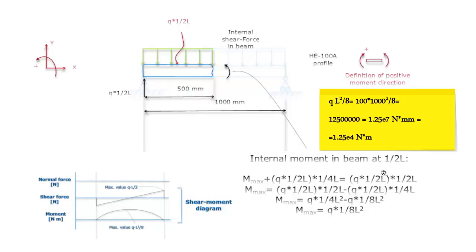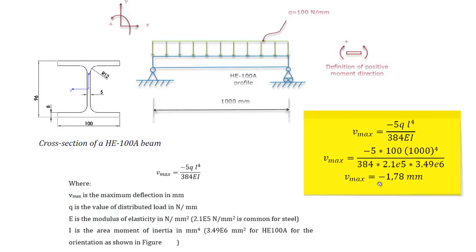So now I've used a free online tool, Autodesk Forceeffect, to get the shear and moment diagrams of this beam, which is convenient. Now, if you were to have a more commercially available FEM software package, you would also be able to analyze this profile and analyze the maximum deflection. That's not yet possible with Autodesk Forceeffect, maybe in the future, but at this moment it's not yet possible. But you can use Autodesk Forceeffect to verify your results, which is always better than not verifying anything at all.